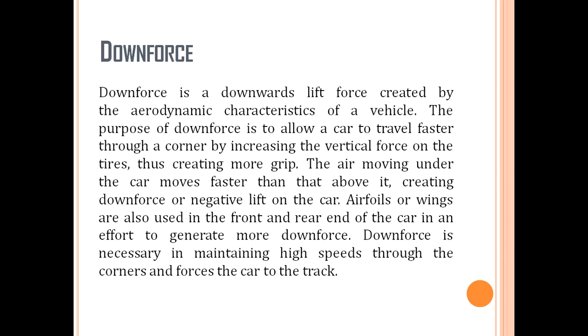Okay, so downforce is a downward lift force created by the aerodynamic characteristics of a vehicle. The purpose of downforce is to allow a car to travel faster through a corner by increasing the vertical force on the tires, thus creating more grip. The air moving under the car moves faster than above it, creating a downforce or negative lift on the car.